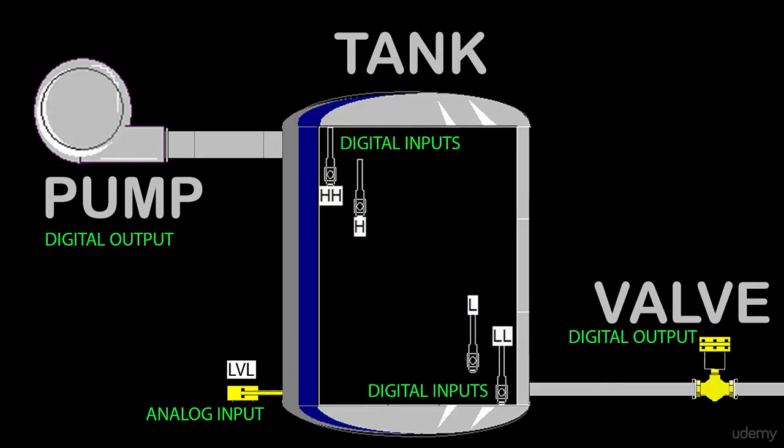That's our system. And we can toggle between our controls. We can use digital level for some examples, we could use analog for others, or we could actually use them redundantly such that we rely primarily on the digitals, but we fall back on the analog for redundancy just in case it detects a high high or a low low. So we've got some options in the system we can play around with, but the goal in this section is not going to be to program this scenario perfectly.